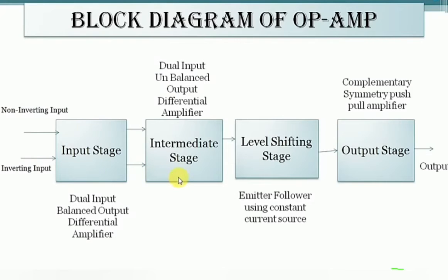We know that without using coupling capacitors, one drawback is that the DC level or the DC biasing voltage level propagates from one stage to another stage through the chain of differential amplifiers. This may cause the transistor to enter into saturation. Due to this, a distorted signal is present at the output stage due to clipping.